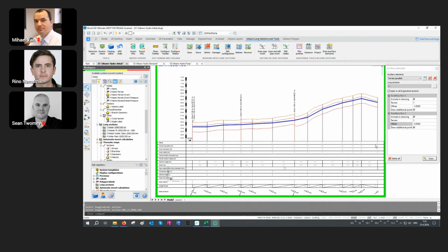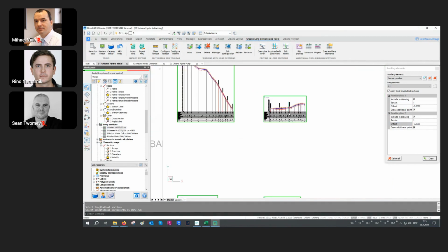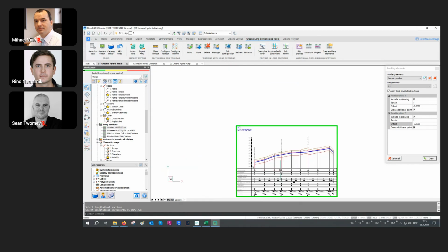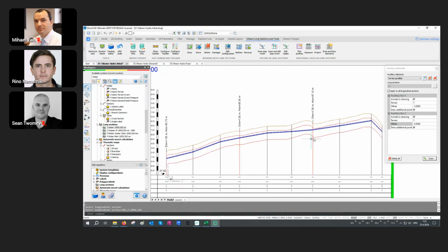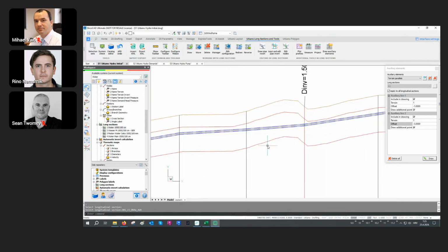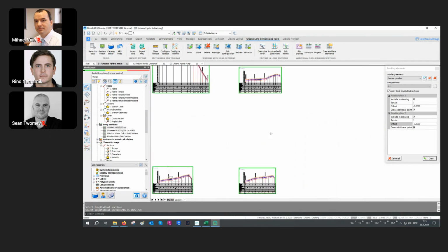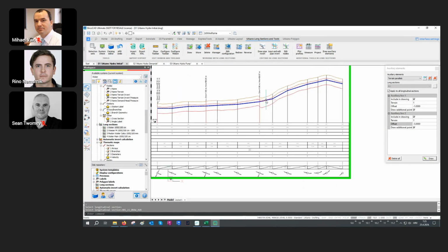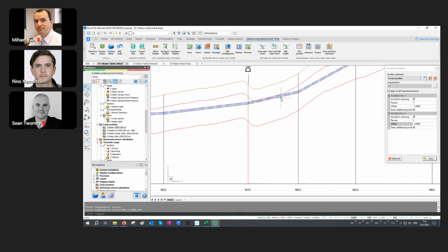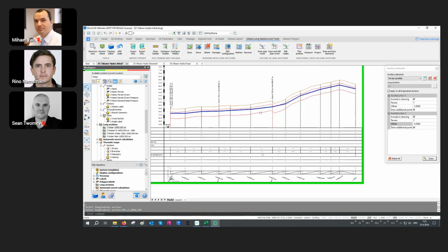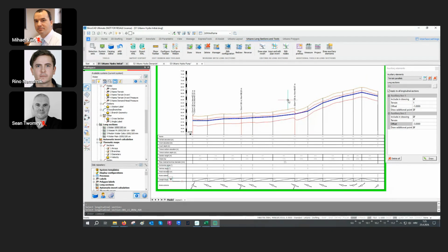So now when I click draw, you will get these helping polylines that will tell you, for example, if somewhere your pipeline is too shallow or too deep below the terrain. So here, for example, I have one such issue, and now I will show you how you can precisely define the pipe elevations.